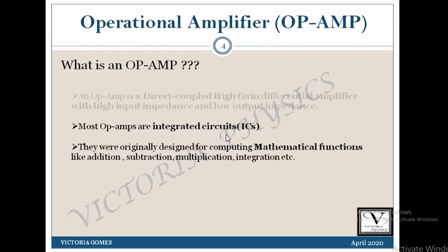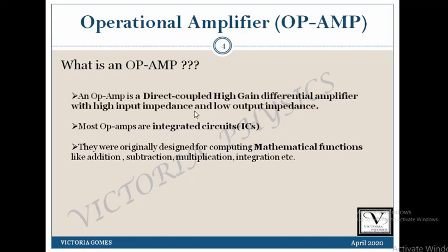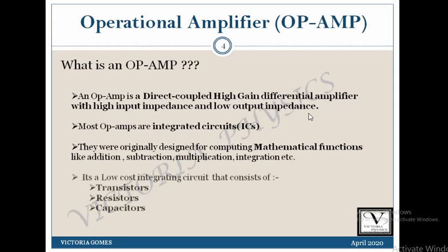So, operational amplifiers are able to amplify a signal due to an external power supply. The name derives from its use to perform operations on a signal. Hence, an operational amplifier is a very high gain differential amplifier with high input impedance and a low output impedance. We will go into a detailed discussion on this differential amplifier later on, but for the time being, let us concentrate on the basics of the operational amplifier.